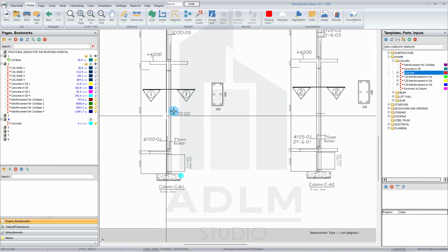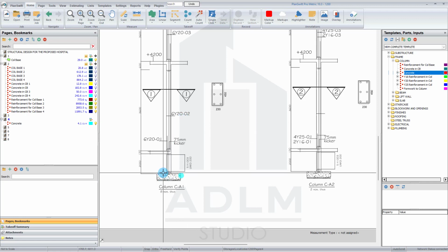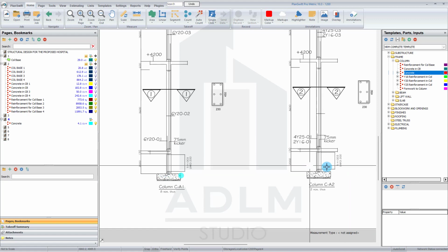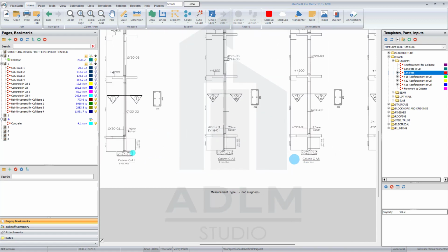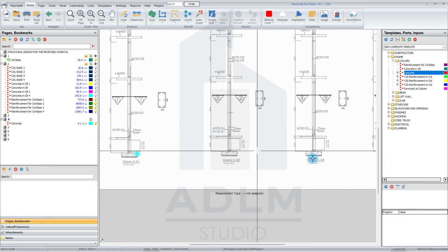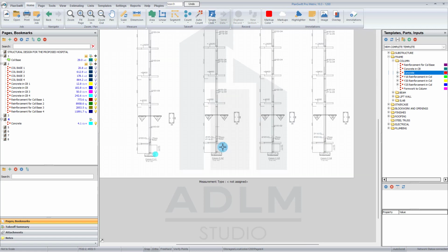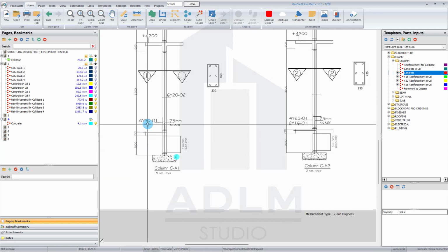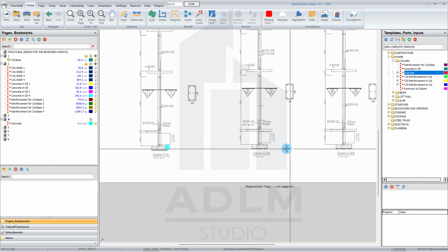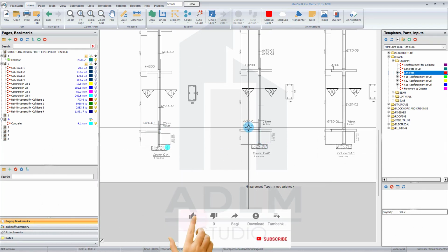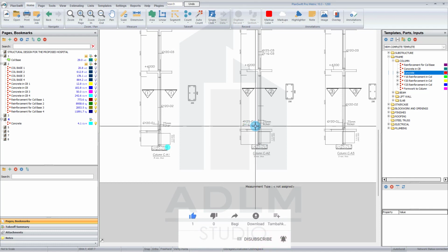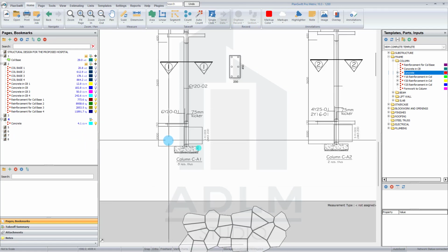Now here, we have Y20 bars. This is saying we are using the Y20 bars for this coming from the foundation. Same goes for this. This is Y16. This is a mixture of Y16 and Y25. This is Y20. This is a mixture of Y16 and Y20. So we have 2 of this column using straight 6 of Y20. Then we have 2 having a mixture of Y16 and Y25. I'm sure most of you will be confused at this stage. How do you go about it? It will seem stressful, but honestly it isn't. Okay, let's go about it now.